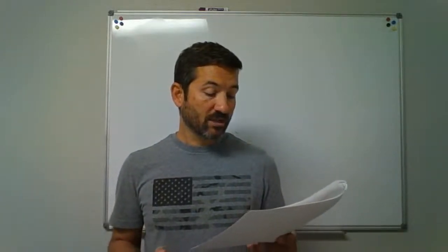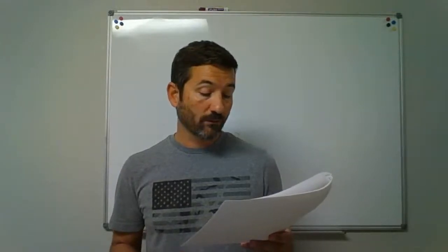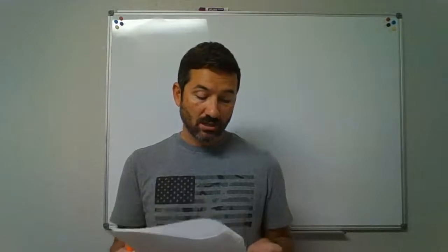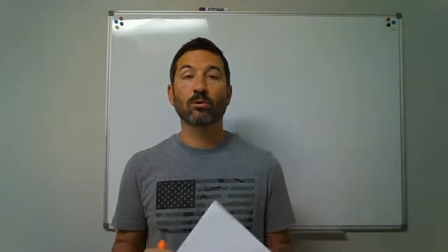Question 20. An air admittance valve should be installed at least 4 inches above the horizontal branch drain or fixture drain being served. Is that true or false?